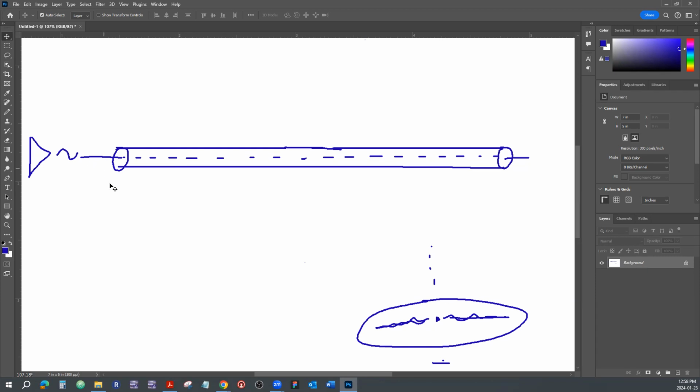But what we're interested in is the interface between the output of the amplifier and the beginning of the cable. The amplifier only cares about, and is only able to see, how easy or how difficult it is to insert the wave into the cable. Which means there's absolutely no difference to the amplifier as it works, whether the cable is very long or very short. It only cares about this spot right here.